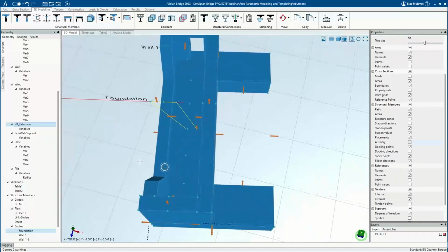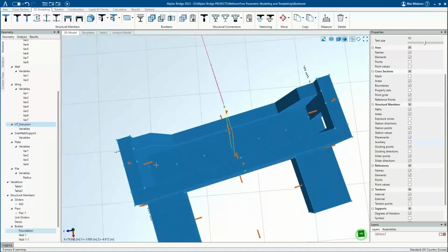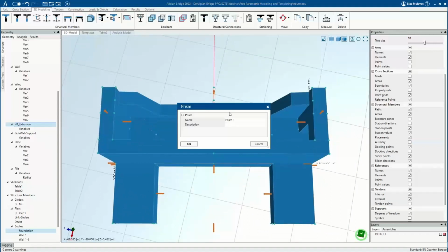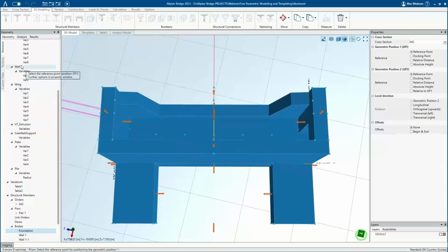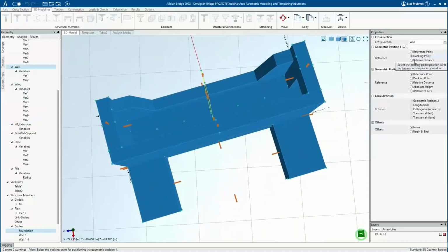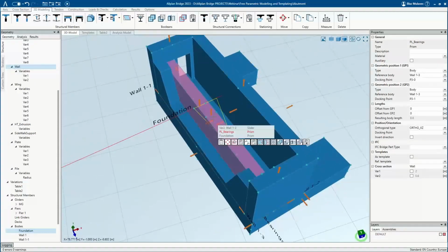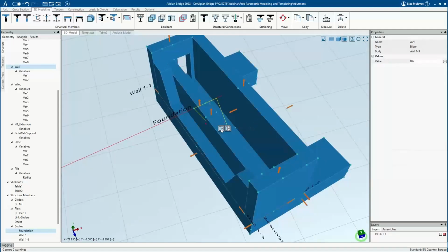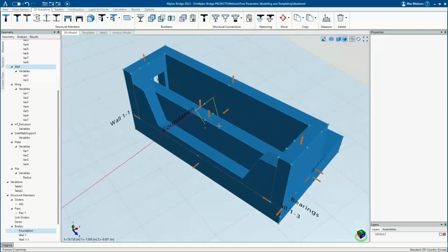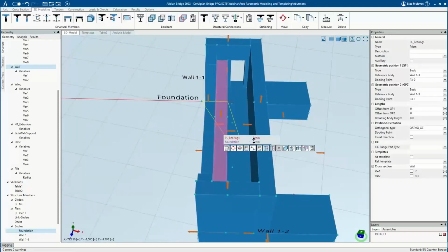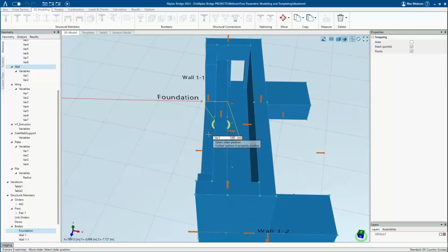Now further, I would like to model a small plate here behind the wall where our bearings will be placed. So for this we will say plate for bearings, and we will again use our wall cross section, which we will define between 2 docking points. So the first one, the second one, and again we will adopt this prism to our desired dimensions. We will use the slider, pardon, wrong one, so this one with, so prism bearings, slider, and this one for the height.